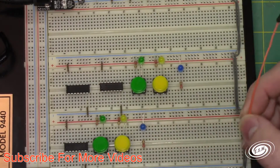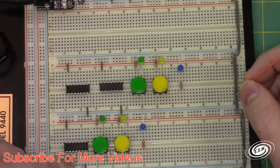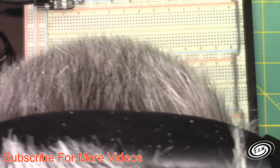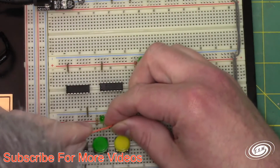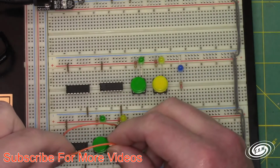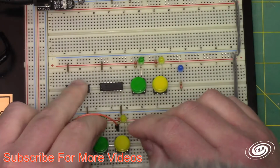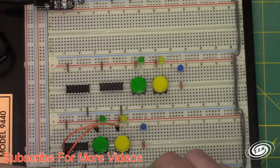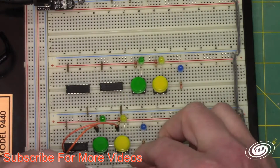I'm going to use this first chip here. So my inputs are 1 and 2. I'm going to pull those low through the resistor. I'm going to go to B, pull that low through the resistor. And then when I press the button, it'll go high through the diode, or the LED. And then my output's going to go to this blue LED.